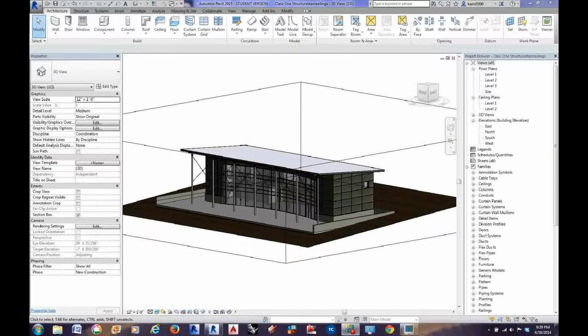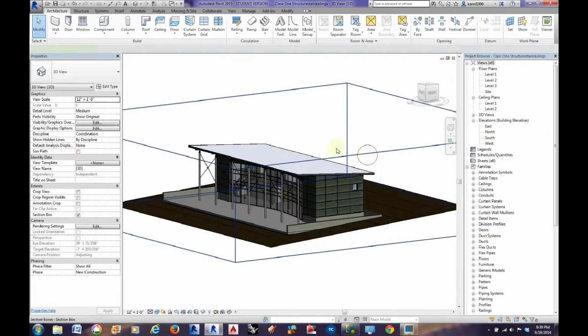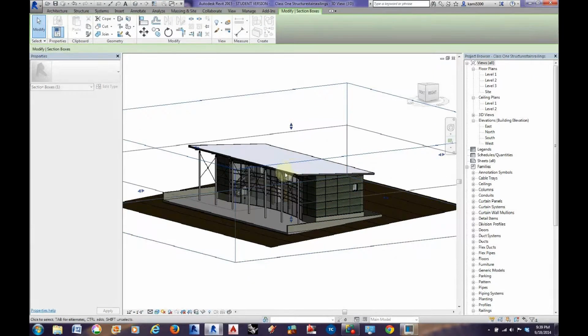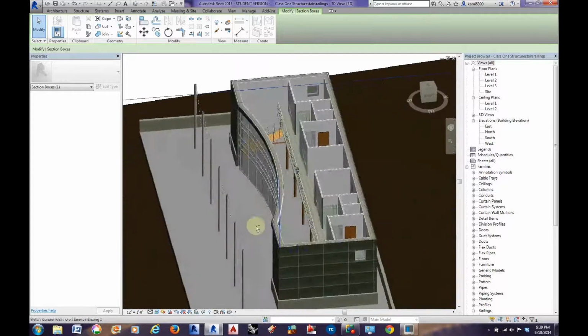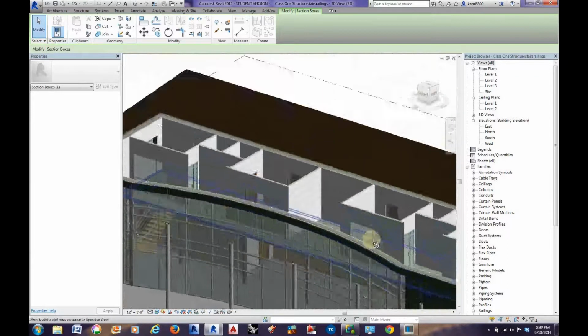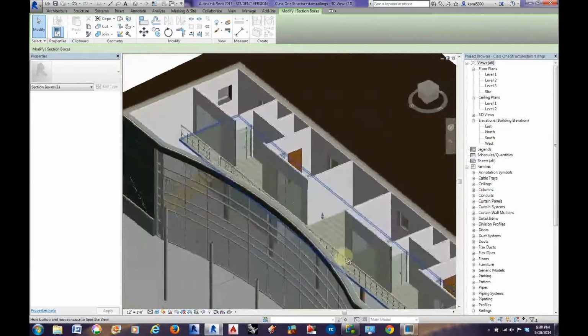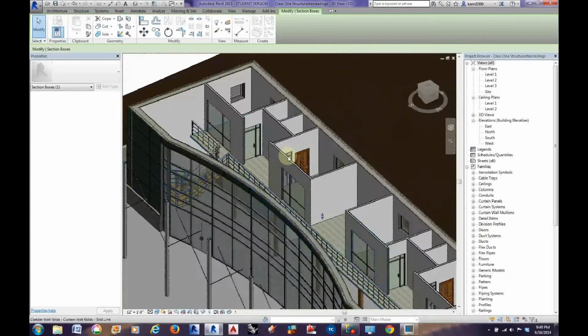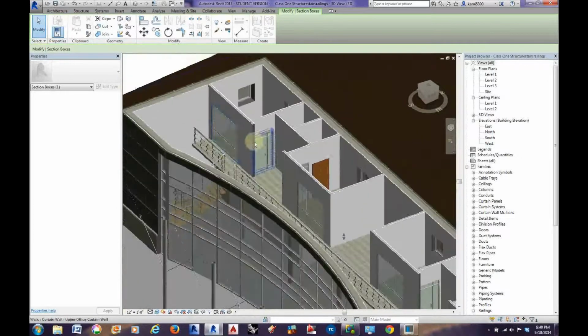Okay, everybody, this is in-class assignment 5, part 3: custom stairs, custom railings, interior partition walls, and ramps. So I went ahead and added in some custom railings and stairs, and then also the interior walls on level 1 and level 2, including the curtain doorways,